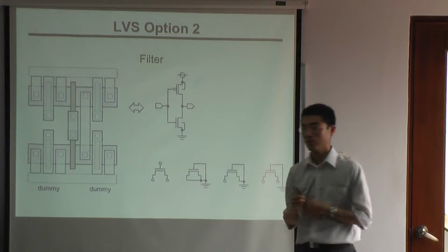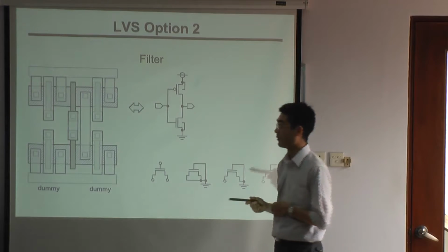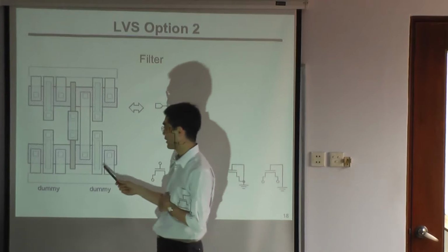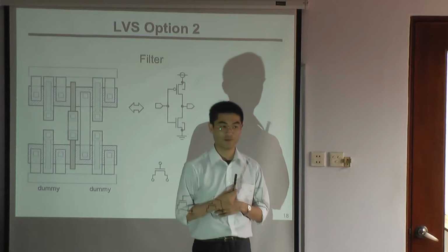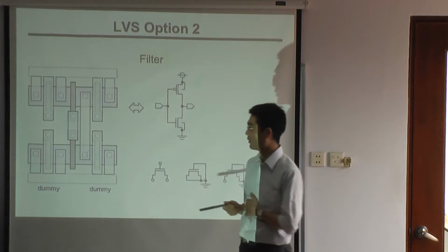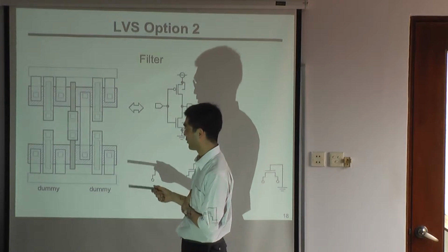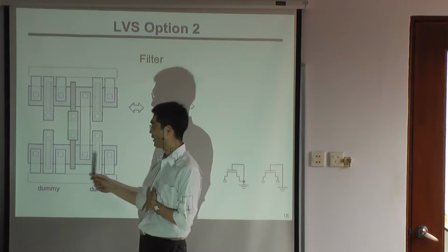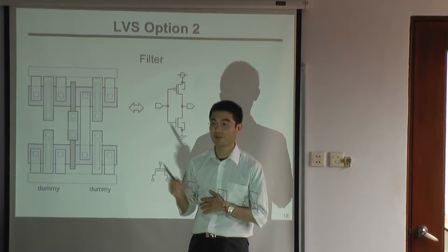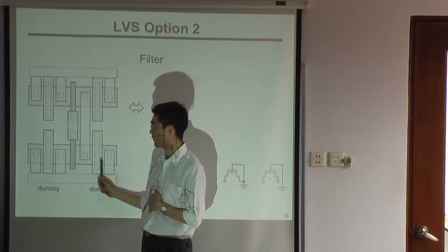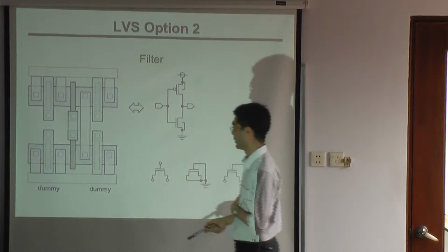And what kind of filter do you use? It depends on what kind of dummy transistors you have. Some technologies do not need any dummy transistors, and some technologies have to have dummy transistors.